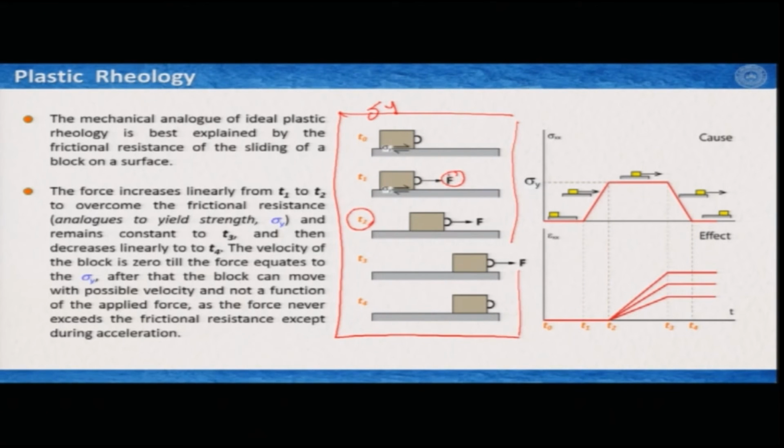This F has closely reached or slightly above this sigma y value, and once I cross this sigma y value, this block has to move, and as you can see in this image, this block has moved. And if I continue applying this force, the block would continue to move, but at time t4, if I remove the force, the block stays in its original position, it does not come back to where it is. So, it is not essentially, not at all, an elastic deformation.